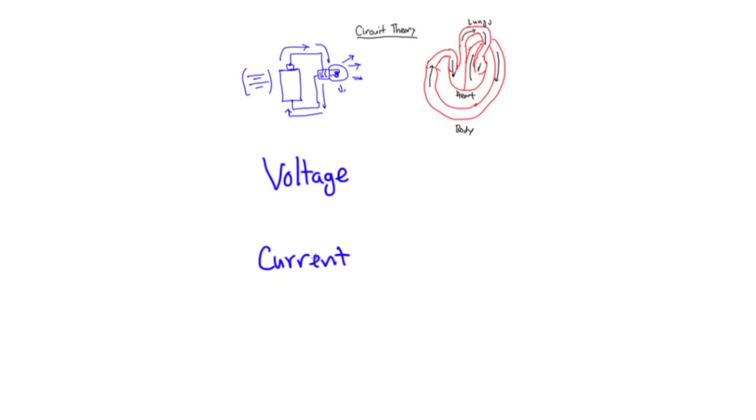In fact, there's a relationship that corresponds the voltage to the current, which is called Ohm's law. What this states is that the voltage is equal to the current times the resistance of your component that you have in your circuit. In this instance, with the battery model, we have a voltage gradient over here, but what limits the current is the inherent resistance of this light bulb. The filament has a resistive property, and because of that, there's a limited amount of current. As you can see right here, with a greater amount of resistance, you have a reduced amount of current if you have a constant voltage, and vice versa.